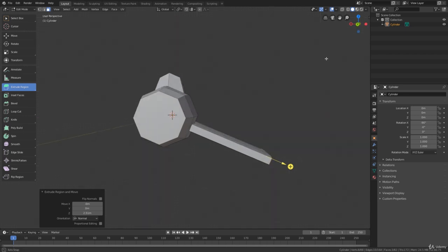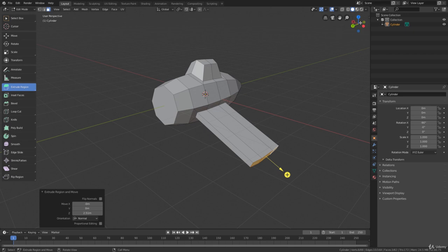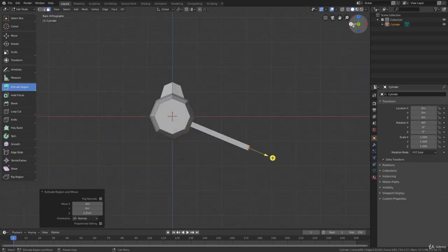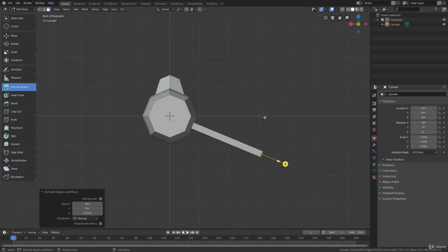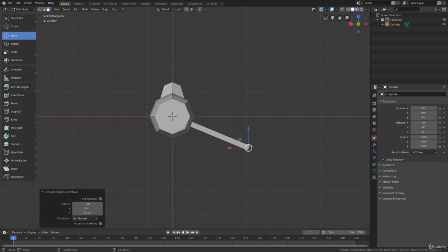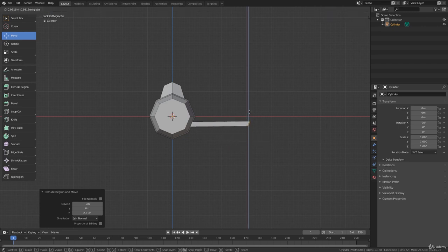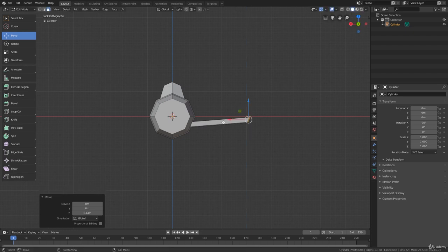But that's not a big problem, because the important thing for us is that the sides of the airplane are aligned with the x-axis of the 3D view. This way, the mirroring tools that we are going to use in the end are going to work properly. So now I can select the Move tool and move these polygons of the tip of the wing up a bit. I actually want this to be pointing up a bit, okay? So it has this small inclination.